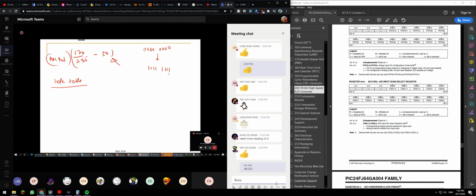That's the reason in those days, with microcontrollers, a lot of the time they built their own lookup table. Of course, this lookup table is not stored in the RAM, it is stored in the flash memory by using constants. For example, let's say this is 8-bit, I say temperature high.